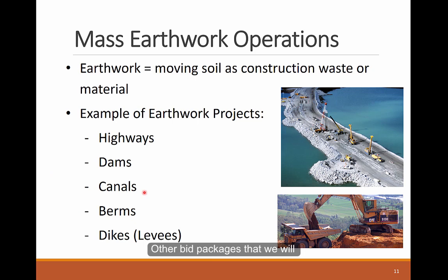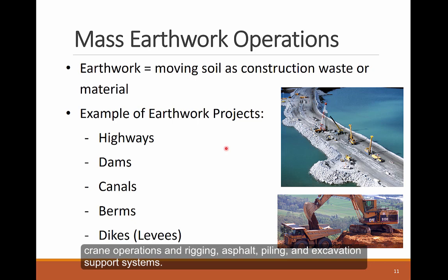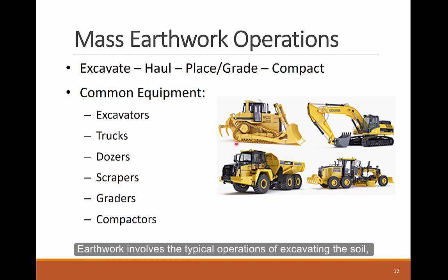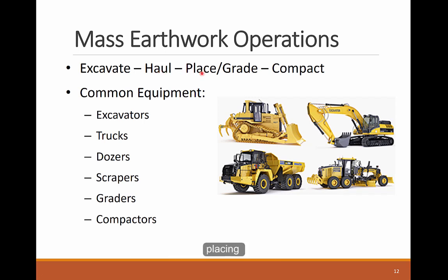Other bid packages that we'll cover in this course include concrete structures, crane operations and rigging, asphalt, piling, and excavation support systems. Earthwork involves the typical operations of excavating the soil, hauling the soil from one location to another, placing the soil and grading it to a specific grade, and compacting it to a specific density.